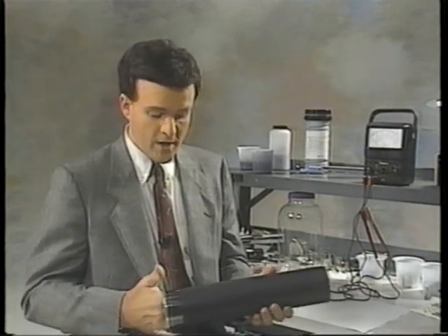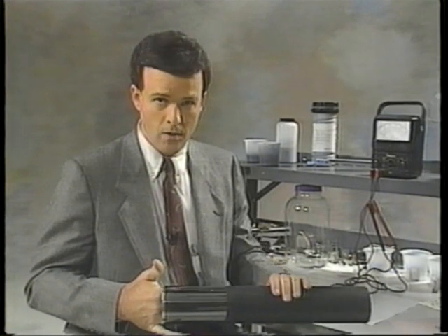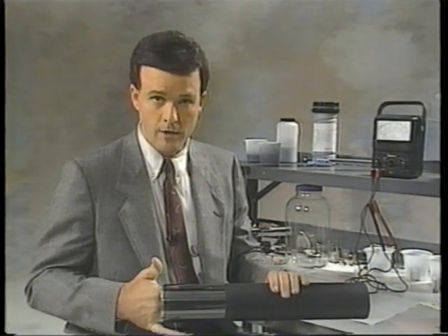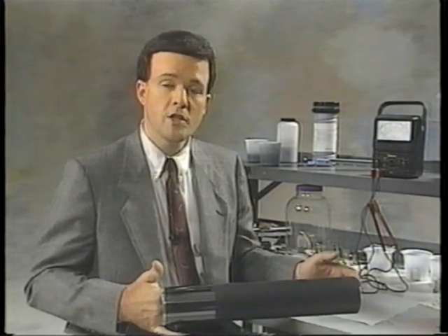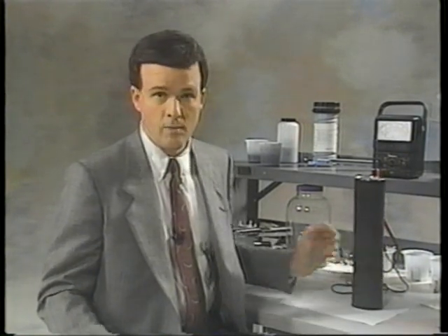Finally, the image reaches the charged photoconductor. The light areas remove the charge from the surface, while the dark areas leave the charge alone. This creates an invisible electrical copy of the original on the photoconductor, a latent image. At this point, the machine has made an accurate copy of the original, but it's not in any usable form. Can't even see it yet. The next step in the copy process will make the image visible: development.